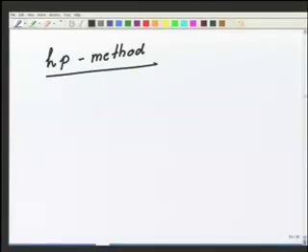So in the HP method, what is done? Both the H and the P are suitably changed in order to get good convergence of the solution. Okay. So this is about the convergence of the error in the strain energy, or how does the strain energy of the error converge. Now obviously there are other questions that come to mind, which is how do the pointwise values of the error behave.